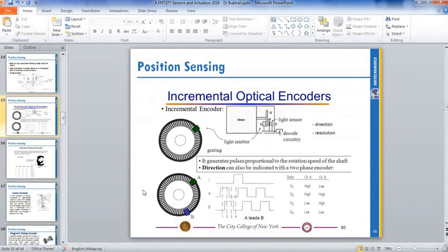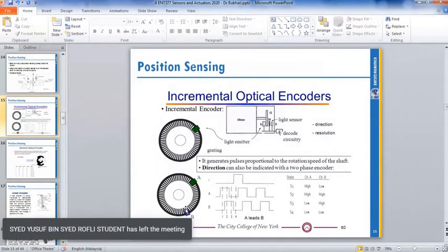Compared to the incremental one, if you turn off your robot, when you turn it on back, although the sensor is located at this position, it doesn't know the current angle of your joint, because your reading is only high-low.